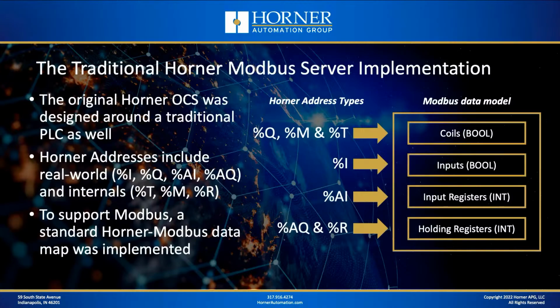We had real-world AIs, which mapped nicely to input registers. And then we had a couple different types of read-write integer-based data, including real-world outputs, analog outputs, AQs, and internal integer data, or %R. So those were all the Horner address types, and it just made sense to map those over to Modbus data types because they were very compatible.